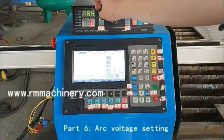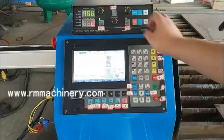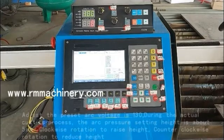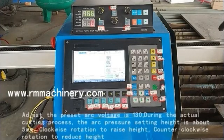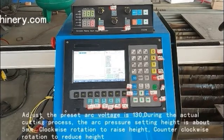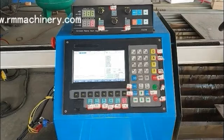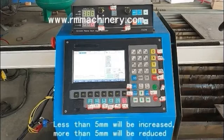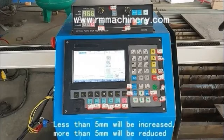Part 6, Arc Voltage Setting. Adjust the preset arc voltage to 130. During the actual cutting process, the arc voltage setting height is about 5 mm. Clockwise rotation raises the height, counterclockwise rotation reduces the height. Less than 5 mm will be increased, more than 5 mm will be reduced.